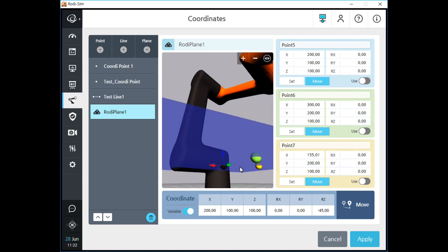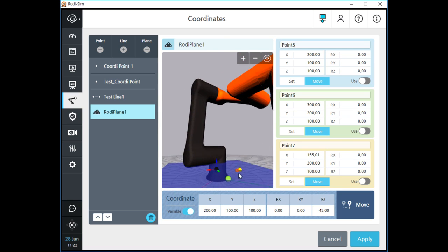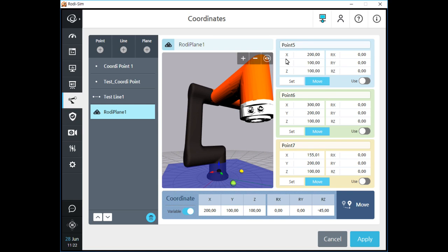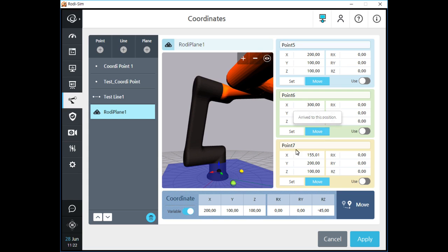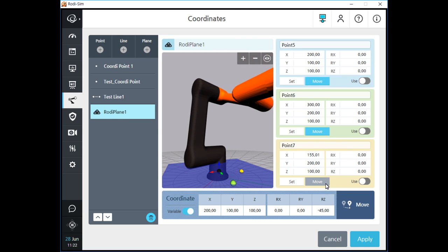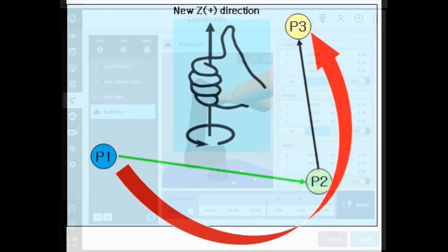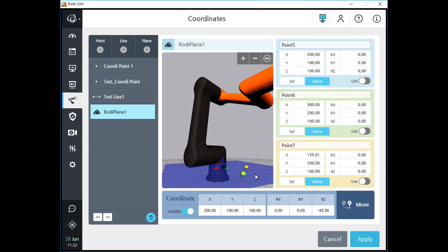Let's imagine a virtual circular arc with an arrow counterclockwise, which includes the 3 waypoints in turn. Make a similar arc with your right hand finger. At this time, the direction of your finger must be the same as the direction of the arrow of the virtual arc. And then, put your thumb up. The direction your thumb indicates is the positive z-axis of this plane type coordinate. Because of this z-axis, the sequence of making the 3 waypoints is very important.